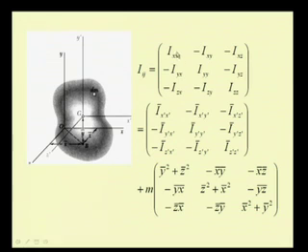So, we apply that for each of these terms, and when we expand it and write, we have it as the inertia tensor in the centroidal axis, that is I bar x prime, I bar x prime y prime. This is nothing but the product of inertia in this plane x prime y prime. In the same way this I bar x prime is nothing but the second moment of this rigid body with respect to this centroidal axis x prime.